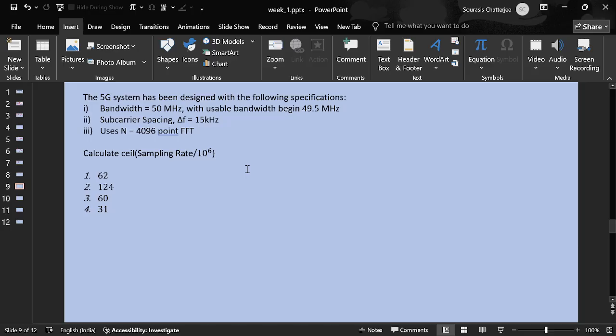And how exactly is having multiple carriers going to help us? Channel estimation and equalization is easier, as all the carriers will be orthogonal to each other. Channel estimation and equalization is much easier compared to a single carrier. And how are you making it easier? It's a 50 megahertz bandwidth, right? Yes, a very wide band system. So if you go for a single carrier, it would be almost flat. It is almost piecewise constant, or segment-wise constant.